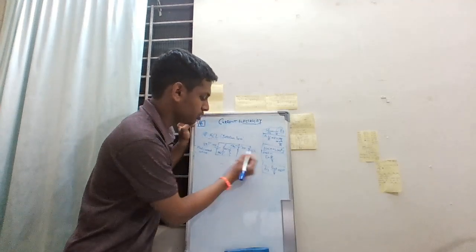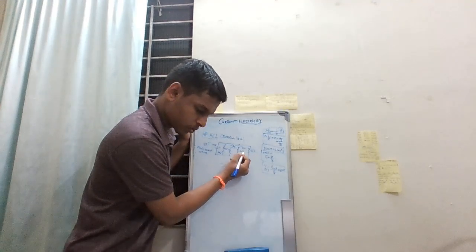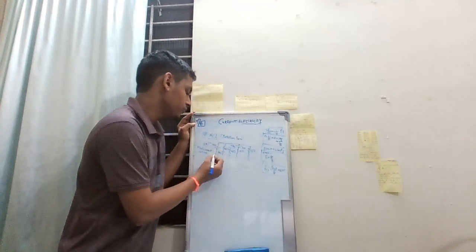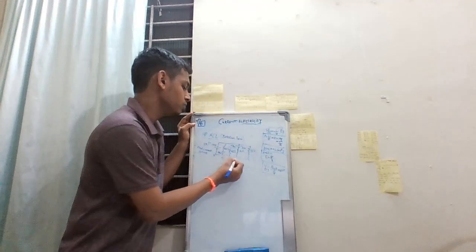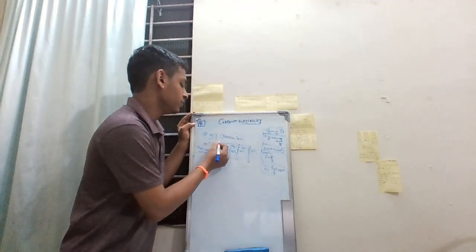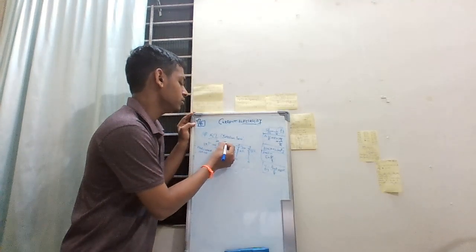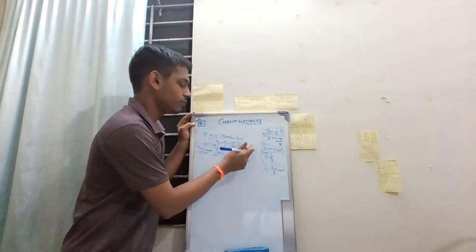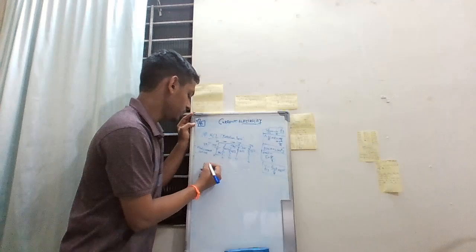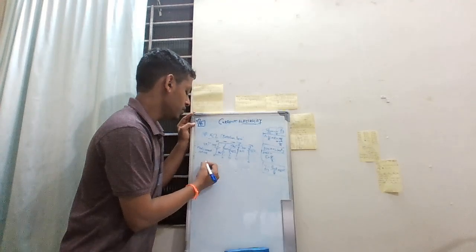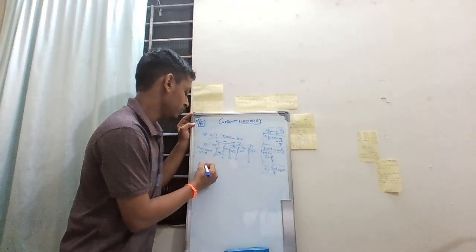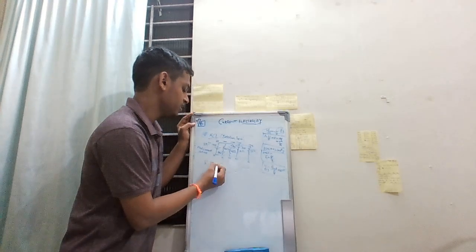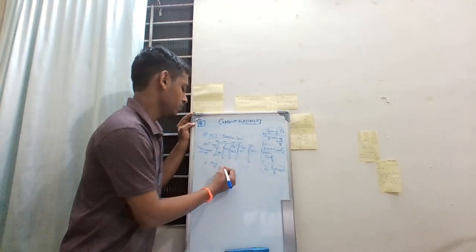This is 5 ohms, this is 10 ohms, this is 26 ohms. So what we basically need to do is, if we consider this as 0, all these would be 0. And if we consider this 100, we can find across this one I equals V by R. So if we consider I5, V by R, 100 minus 0 by 5 equals